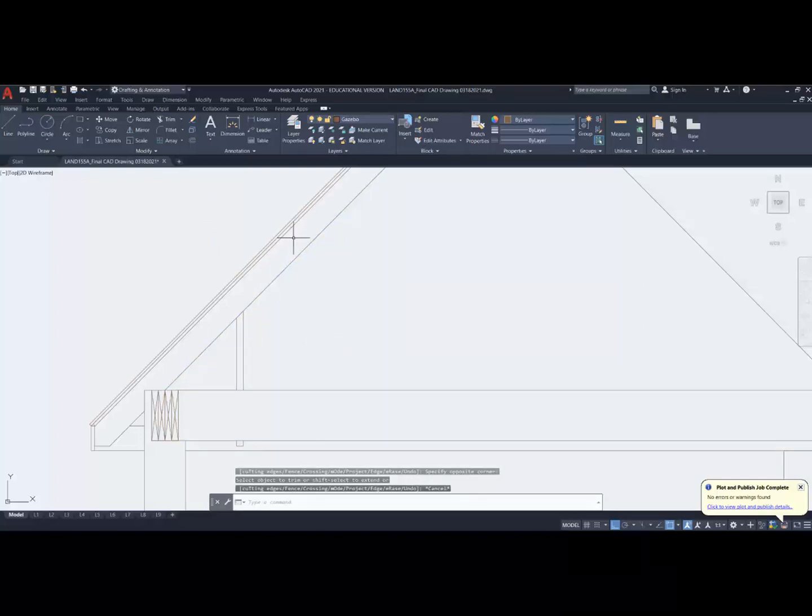So let's try to make sense of this. Here's our ceiling joist. Now I'm using the term ceiling joist. It's a ceiling joist if I'm using any sort of material underneath this. So if I plan on cladding this with cedar planks, this is a ceiling joist. If I don't plan on cladding anything underneath and leaving it open like I'm drawing here, then it's actually considered a rafter. And those are two terms we're going to be studying a bit more next semester.